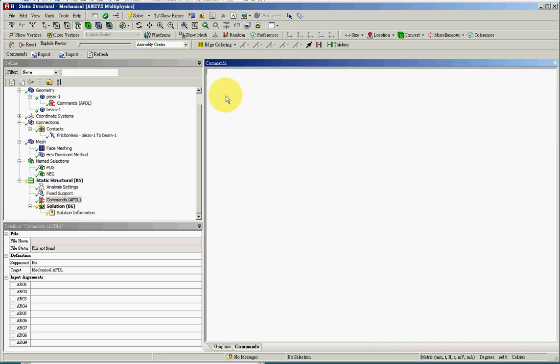and now I can place a command for the loading. D command, positive electrode, volt, 700 volt. D command, negative electrode, volt, 0 volt. So these are the voltage placed upon both electrodes.